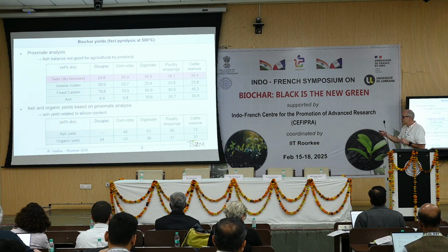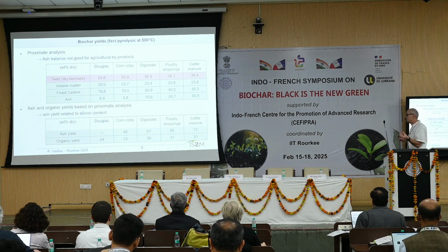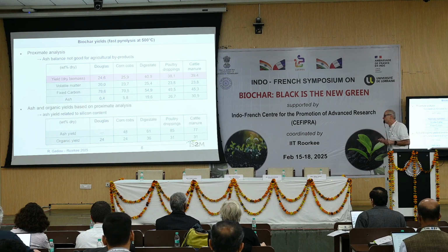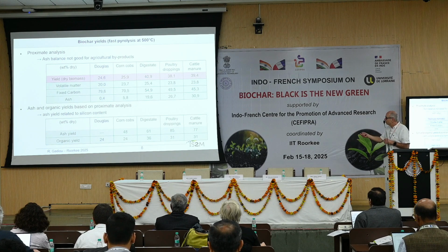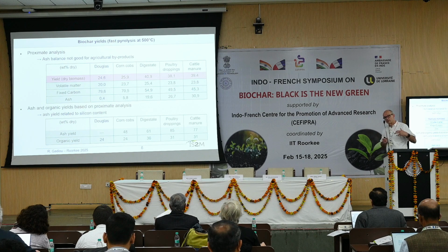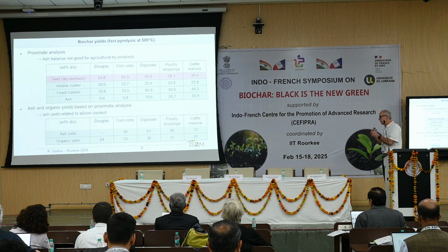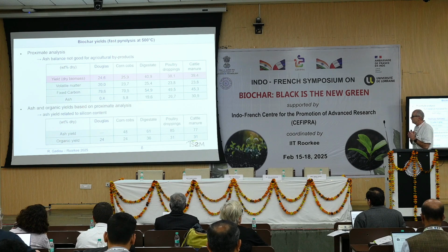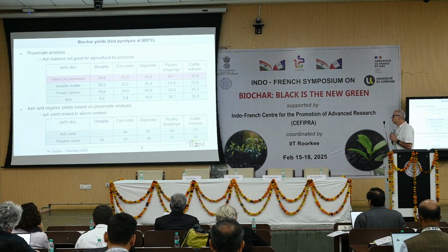An important thing is that if you go to the other mass balance, which is the organic part, that is the fixed carbon and the volatile matter part, you see that you obtain a higher amount of carbon yield for byproduct. So that shows that the mineral matter has an effect, which is a well-known problem that we have in biomass pyrolysis. It shows clearly that the mineral matter has an effect and seems to increase the carbon yield when you use byproduct.